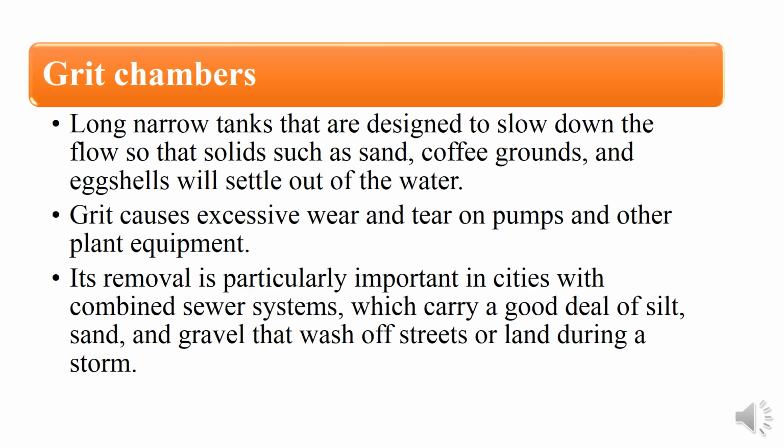Next is the grit chambers. Long narrow tanks that are designed to slow down the flow so that solids such as sand, coffee grounds, and eggshells will settle out of the water. Grit causes excessive wear and tear on pumps and other plant equipment. Its removal is particularly important in cities with combined sewer systems, which carry a good deal of silt, sand, and gravel that wash off streets or land during a storm.